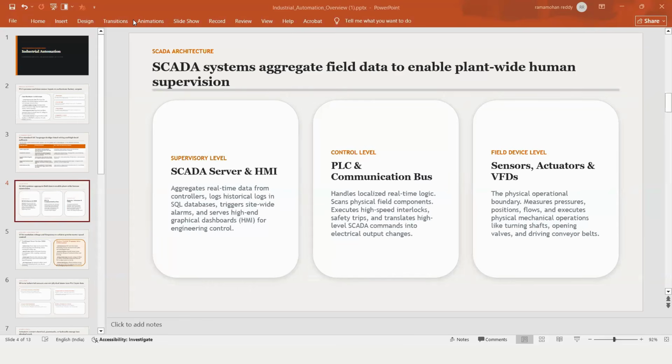It takes the light data of that room and gives it to the PLC, and the PLC compares the set point required for that room with the process value, and then gives the signal to the extra light to turn on or off. This entire activity will be captured in the SCADA and logged as data, so you can look at your data even after a year. That is what SCADA does.